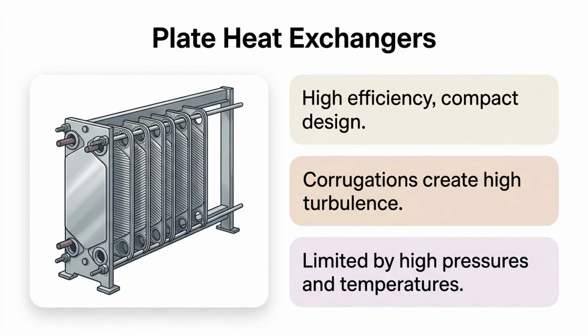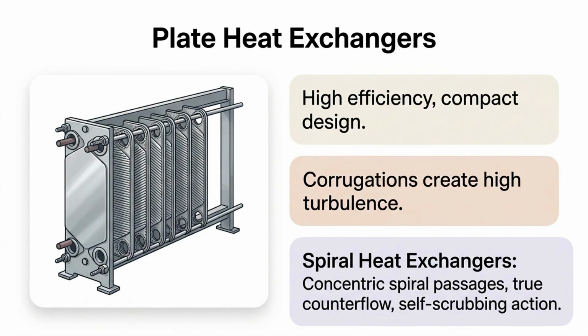A unique variation is the spiral heat exchanger. The plates are rolled into a coil, creating a single, long path for each fluid. This true counterflow design creates a self-scrubbing action, making it fantastic for handling sludges or dirty fluids.